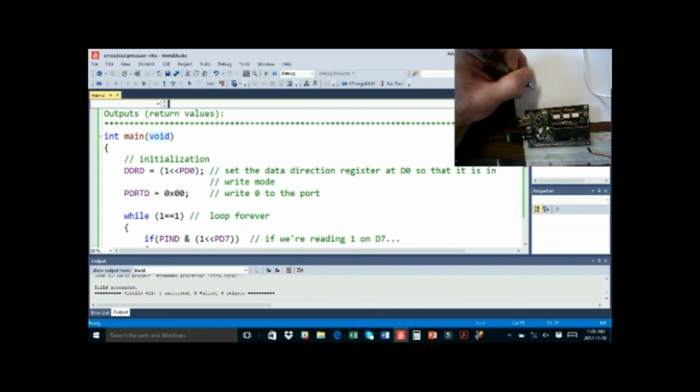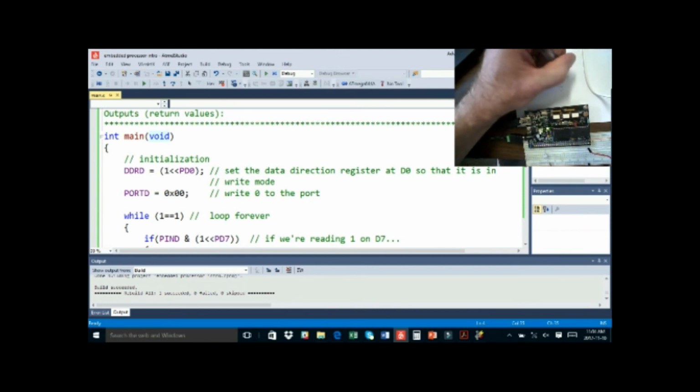That produces 5 volts or 0 over here, and it's going to be feeding into an LED like this and a resistor like this. The resistor that I chose is a 1 kilo ohm resistor. The smaller the value of the resistor, the more light appears in the LED, because the LED intensity is defined by the amount of current that flows in here.